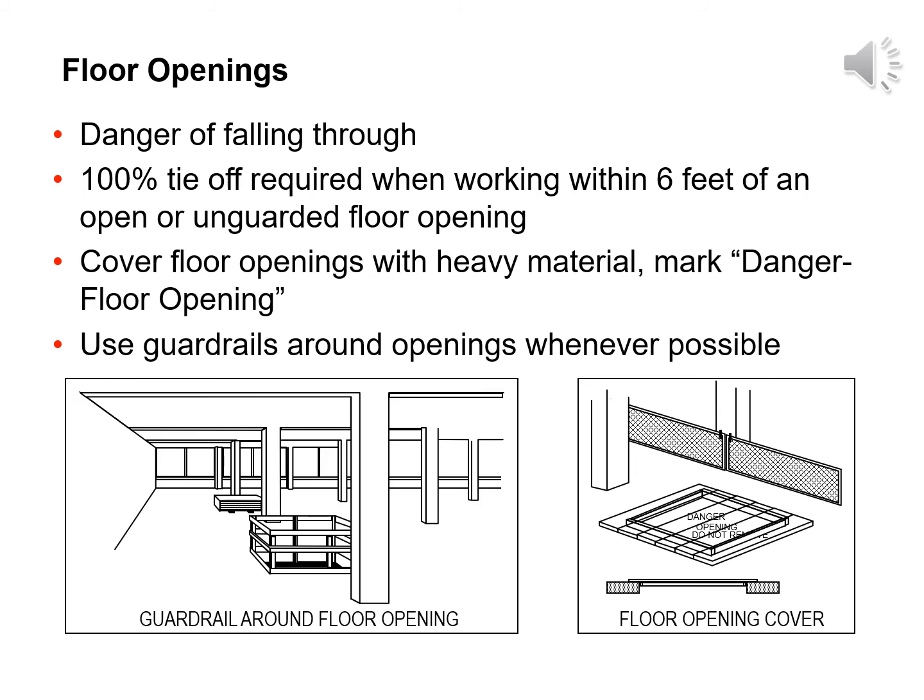Many accidents occur because workers forget where they are standing and fall through the hole they just created. This is why 100% tie-off is so important and required when working within 6 feet of an unguarded floor opening. Always remember to cover floor openings with substantial material, like heavy plywood, and secure it in place with clamps or other means. Be sure to mark the floor opening with a label or marking that reads "Danger, Floor Opening." Guardrails should be installed around any floor opening, even temporary openings, when possible.